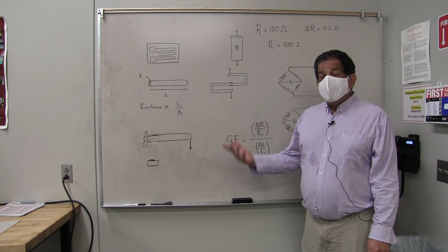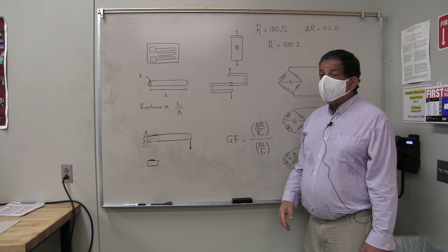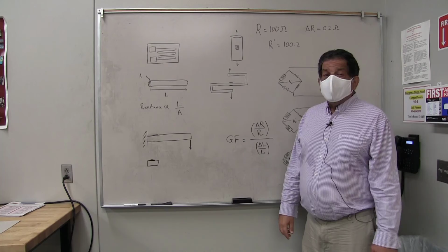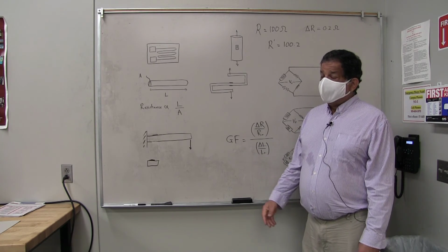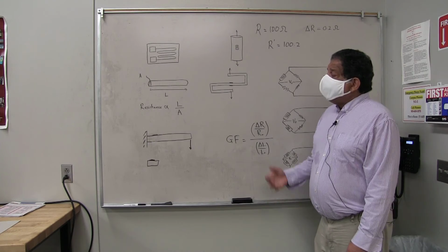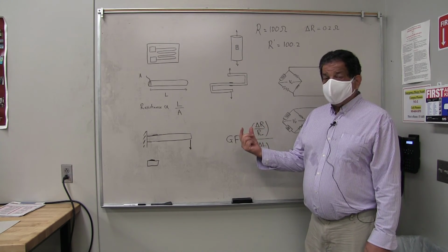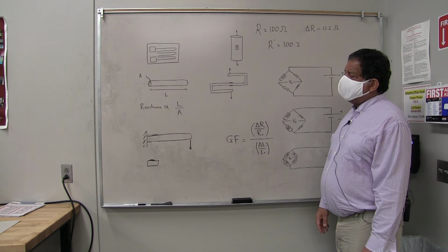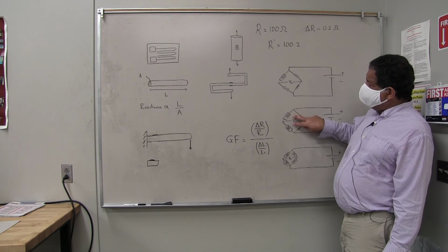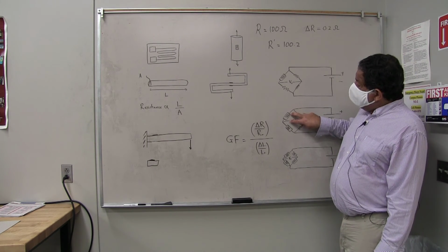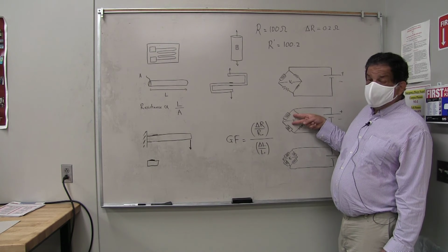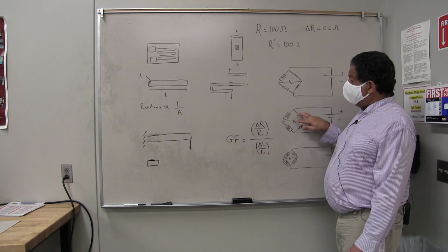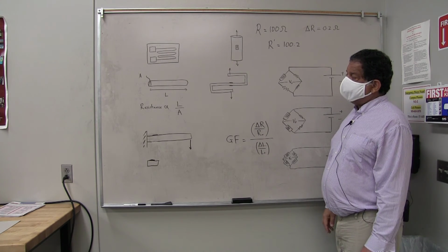But if you were instrumenting the device for travel across roads, let's say, and you put the strain gauges on in the garage of your laboratory, and then you're traveling to Minnesota and you're traveling to Arizona, then compensating for the thermal expansion is a valuable thing potentially. In most cases, if you're interested in automatically rejecting thermal expansion, though, you would do a full two active gauge half bridge setup, or else a full bridge setup, so that you're getting the full benefits of increased sensitivity as well as the rejection of the thermal expansion.